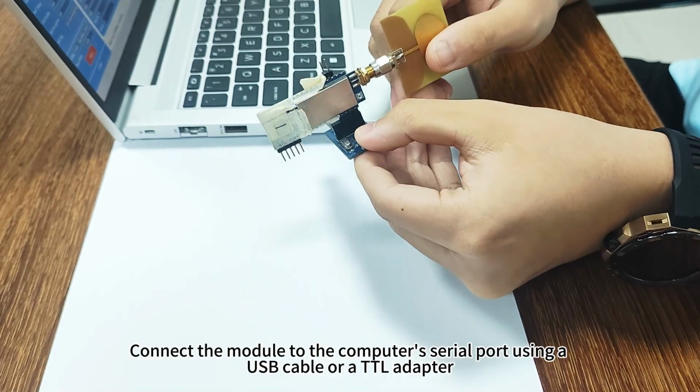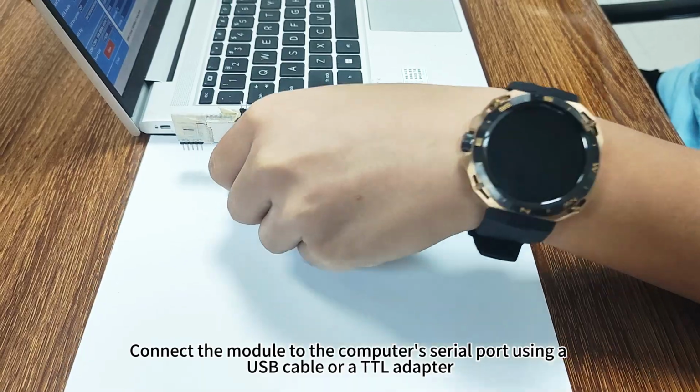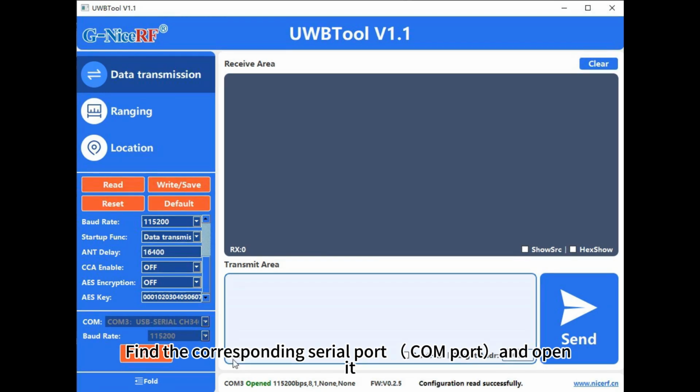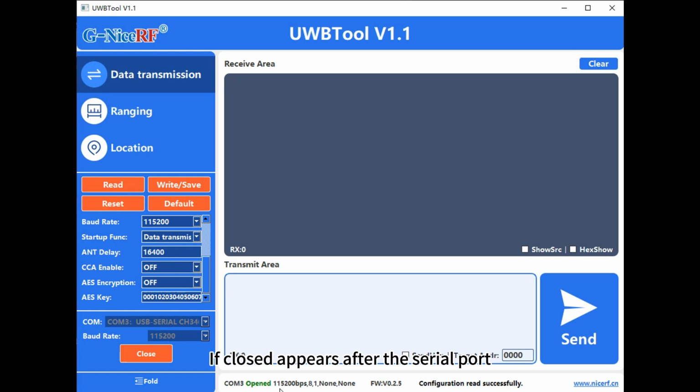Install the antenna, and connect the module to the computer's serial port using a USB cable or a TTL adapter. The status of the serial port can be observed from the serial port section below. If Closed appears after the serial port, then the serial port is closed. If it shows Open, then the port is open.